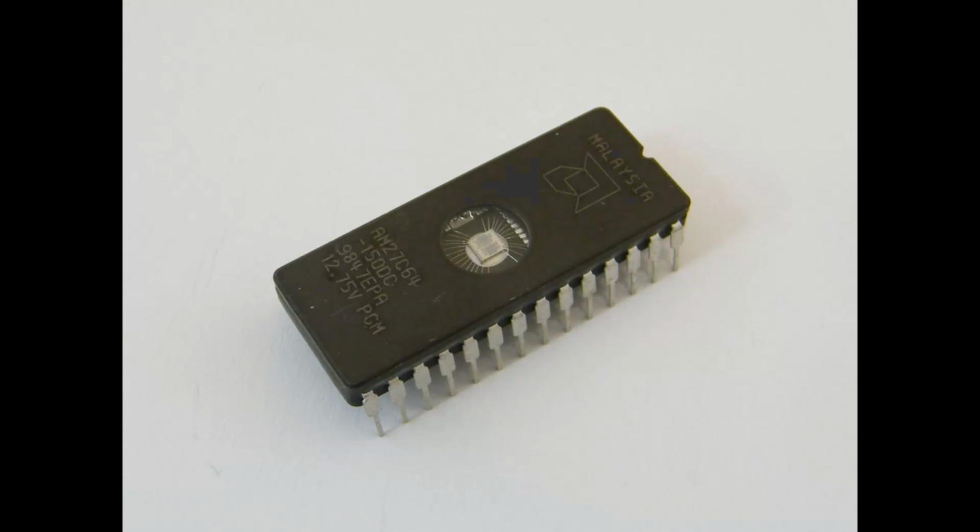It also means that I need another set of data bits. I could wire the data through the same bus and switch sources externally, but one of the things CPLDs are good for is lots of I/O pins. The external character ROM has the address bits driven by the row counter and the same data bus used for regular data input on the CPLD. The data output from the ROM goes to a dedicated set of 8 data inputs. The result is I just need to select which data bus to input from. Amazingly, this is almost the entire design, but there is one more signal I need to worry about.